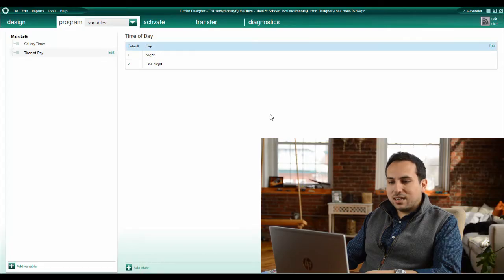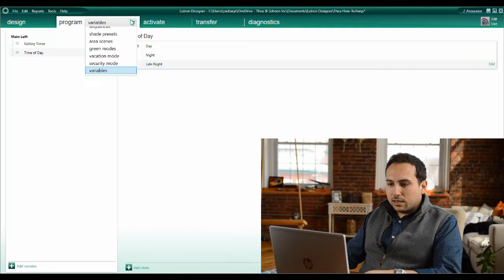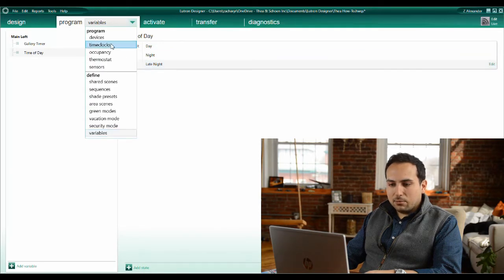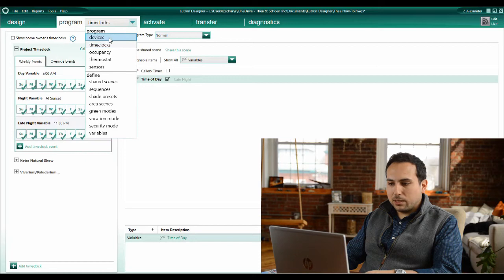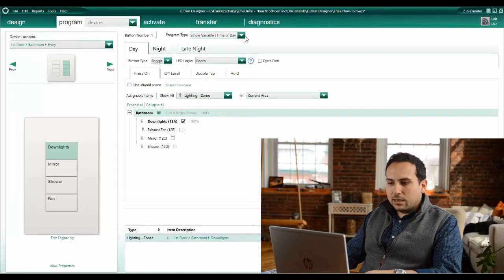In today's video, I'll show you how to create a time of day variable that contains three states: day, night, and late night. Then I'll show you how to create three time clock events that flip or change the state of that variable. Lastly, I'll show you how to apply single variable programming to a keypad button, and then we can perform three different output actions depending on which state the variable is in when the button is pressed.